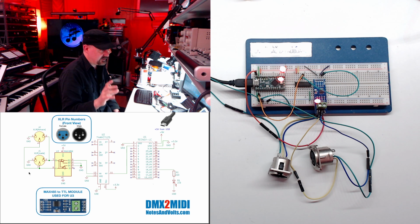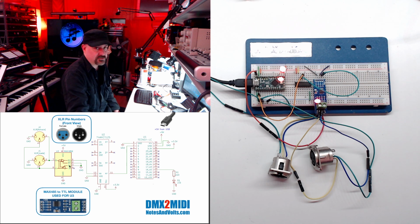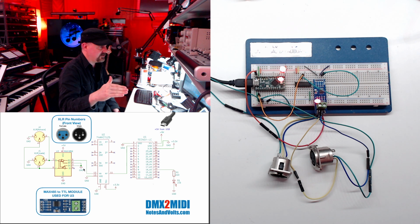The 2 other pins, the DE and RE, are driver enable and receiver enable. If you look here, both of those pins are connected to ground. We do that because we want to disable the transmitter pin and we want to enable the receiver pin. And if you notice, the receiver pin has this little line over it. That means that pin is enabled when you put a low level signal or a ground signal into it.